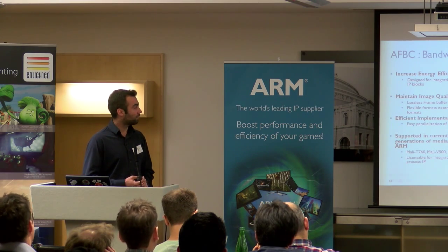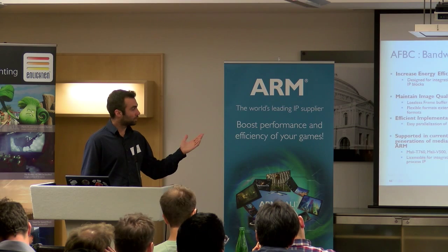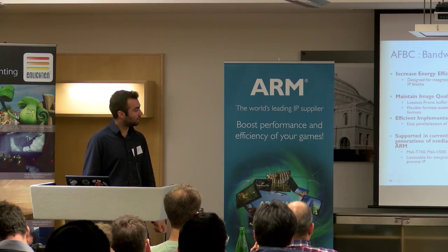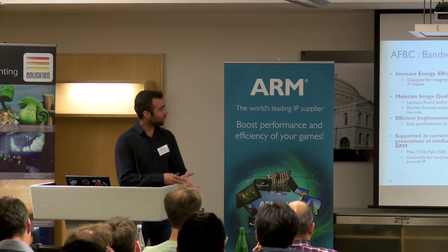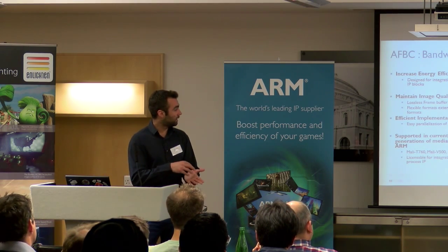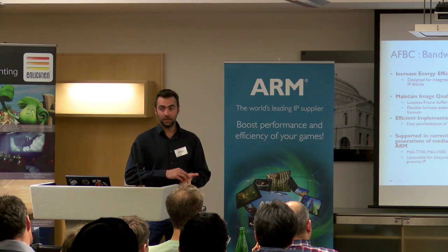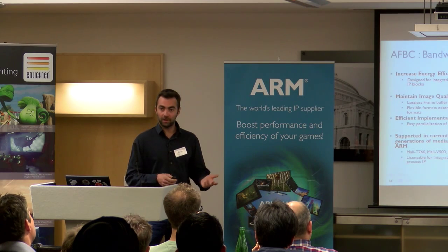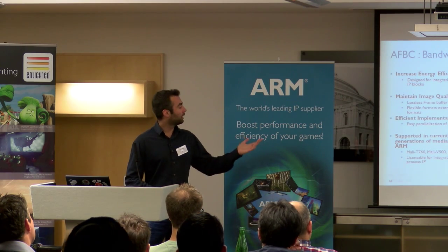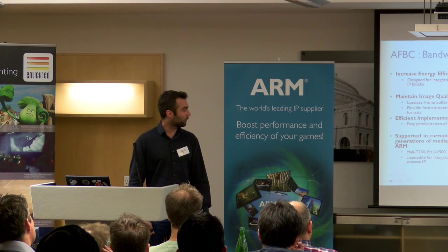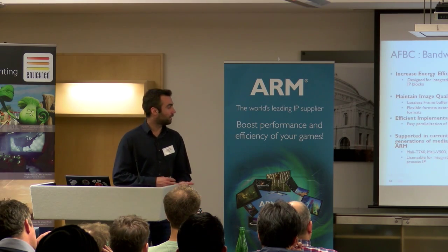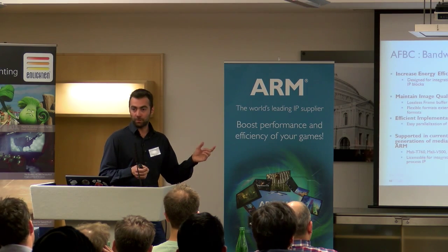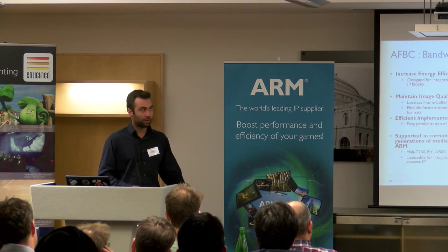We have introduced AFBC in our video codec in Mali V500 and also in our display processor in DP500. And we're also providing AFBC as a standalone block that can be introduced in any third-party IPs that are processing images like ISPs or any other type of processor. And therefore, you can have your whole SoC working efficiently by passing compressed buffers from one IP to the other.